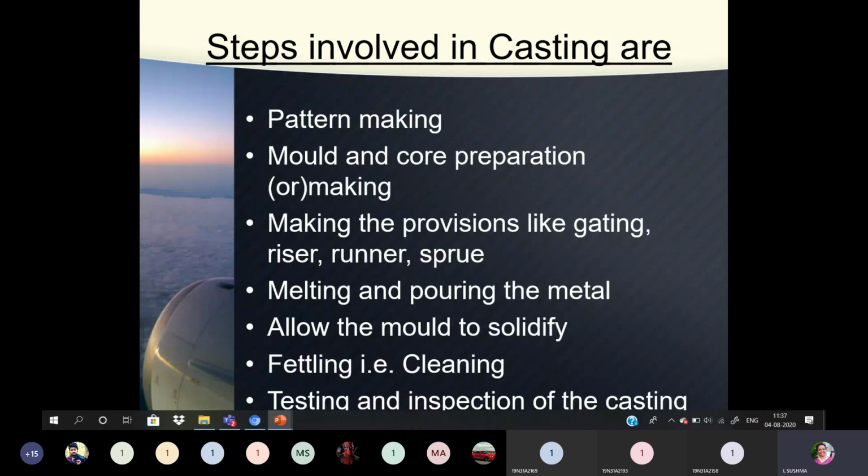What happens after a few days is that you will see some pit has formed there. Have you noticed that? Yes, ma'am. Yes or no? Yes. So in the same way, when you pour the molten metal directly in the mold, the shape will change. So to avoid all this, you will provide some gating system. Gating system means what it will do? It will slowly transfer the molten metal to the mold without destroying the shape. Okay, that is nothing but your gating system.